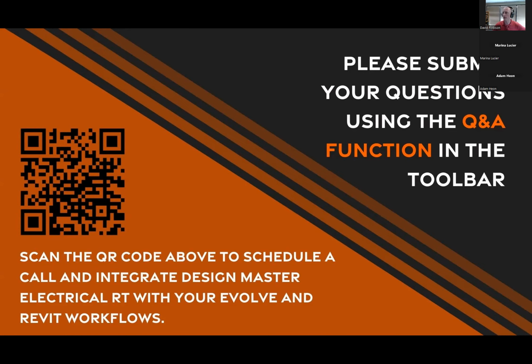And that does include the selective coordination, that we can actually do those breaker curves in our software. Let me assign a breaker curve to this panel. This is MVP3. So we've got the list of breakers. You choose your curve, you give it all the settings. And then we can insert that curve on a drafting view in Revit. That's MVP3. And so there is your curve for that breaker.